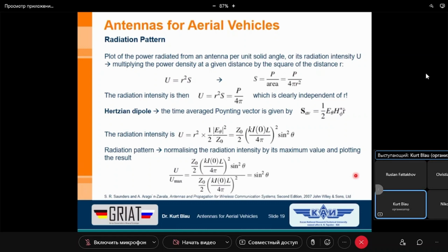We know that the electromagnetic wave travels out as a sphere. That means the wave goes out with the sphere function. Then we know that at a certain distance, the power density must decrease. It cannot be held at a certain value. So at the aperture, the input area of the receiving antenna, with a decreasing power density, we have much less energy. The larger the distance, or this small r, the smaller the received energy.